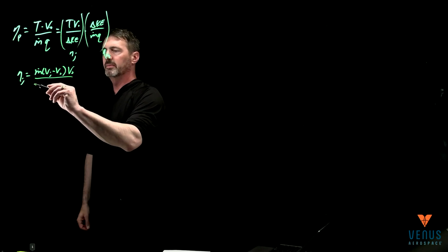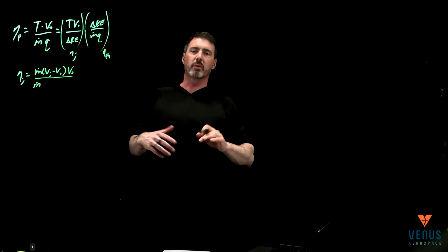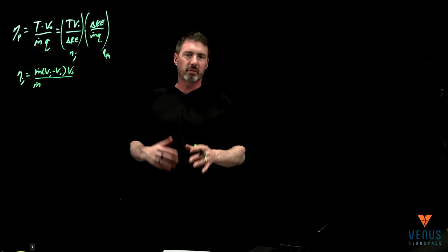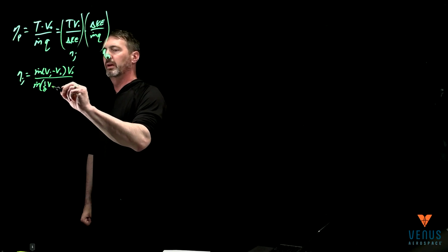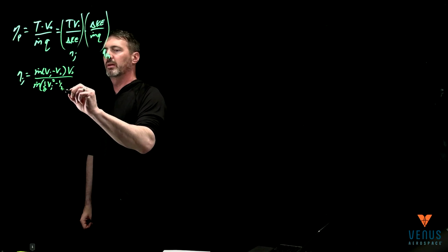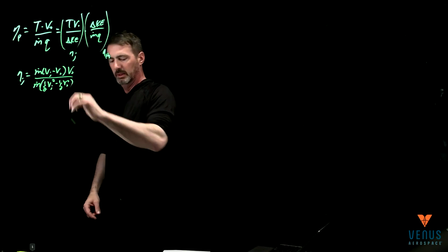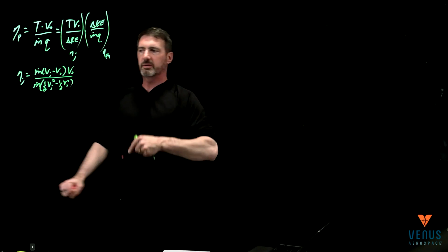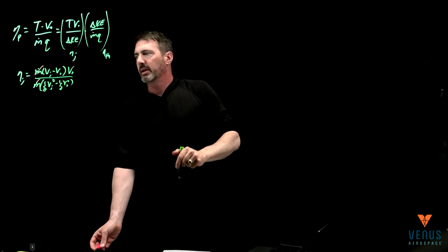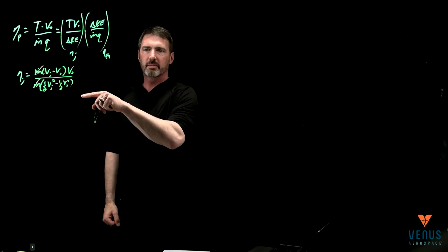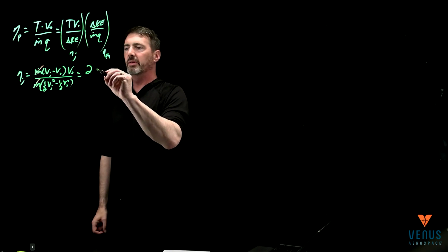The kinetic energy, again because the mass flow is roughly the same, even though there's some mass addition of the fuel that is pretty much negligible, is one half v jet squared minus one half v0 squared. So the mass flow rates cancel out, that's great, and both of these halves are on the bottom, so I get a factor of 2 up top.